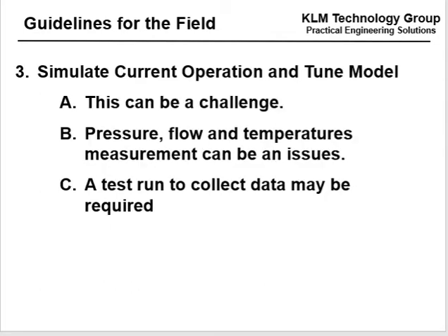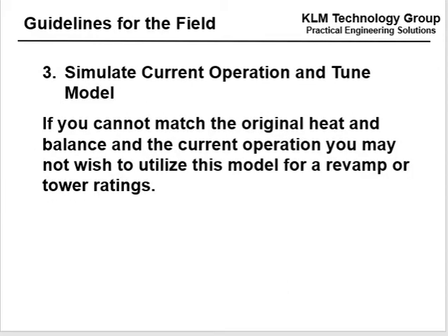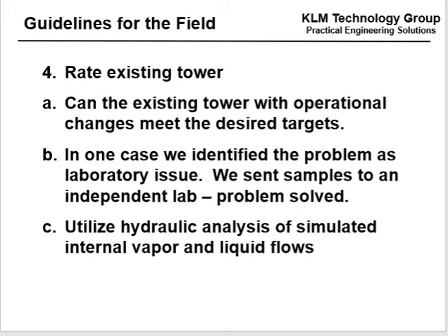Simulate the current operation and tune the model. This can be a challenge. Sometimes not all the instrumentation is there. Pressure, flow, temperature measurement can be an issue. Sometimes you have to run a test run and reconcile the data. If you cannot match the original heat balance and the current operation, you may not wish to use this model for a revamp or tower ratings.